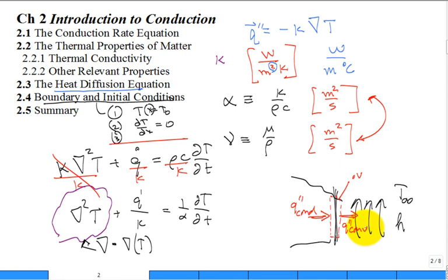It doesn't have any thermal inertia. So, how do you describe Q double prime conduction? By Fourier's law, minus K times the derivative of temperature with respect to X at that surface, equal to, how about Q double prime convection? H times the temperature at that surface minus T infinity. Does that equation make sense?